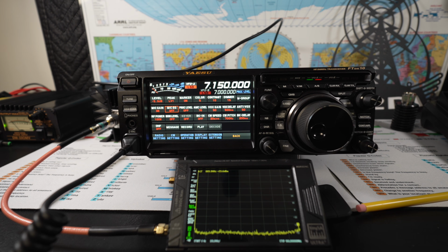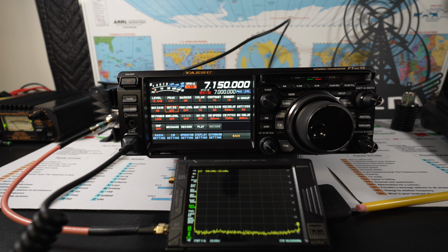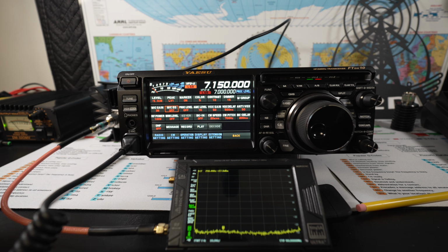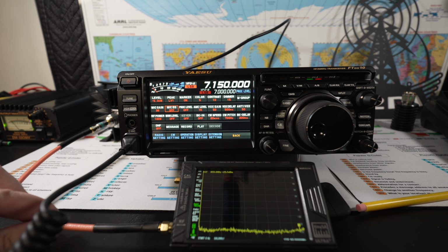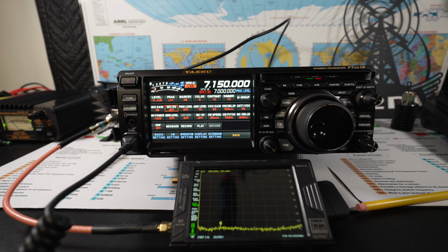Okay, so now I've zoomed back so you can get a big picture of what I'm doing. I have the FTDX10. Here's the output. The antenna output goes into the back of this giant attenuator, which gives me 40 dB of attenuation. It comes through the 20 dB attenuator, so I get a total of 60 dB of attenuation. That comes out to the RF input on the TinySA. So this is the setup. Now I'll zoom in and quickly run through the settings that you need to set on your spectrum analyzer to do the same test if you want to test along.